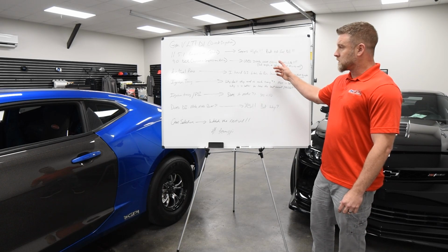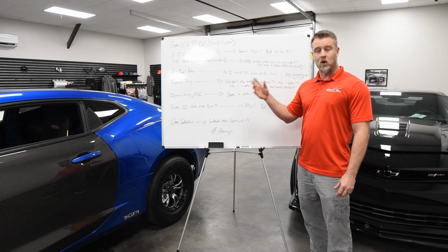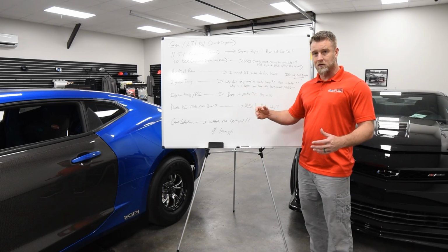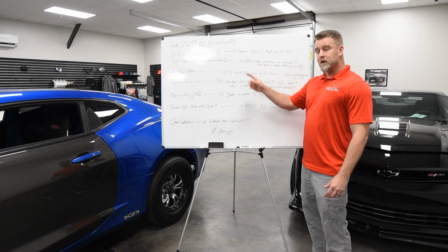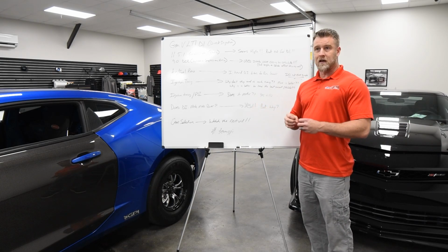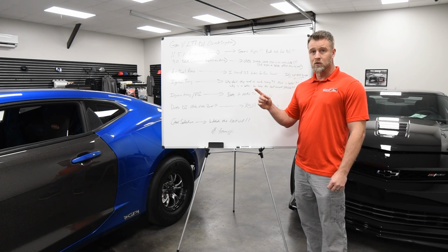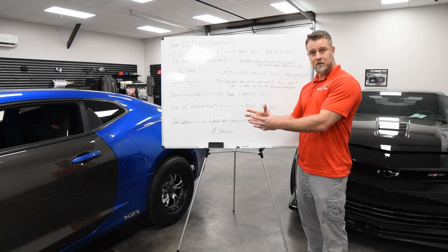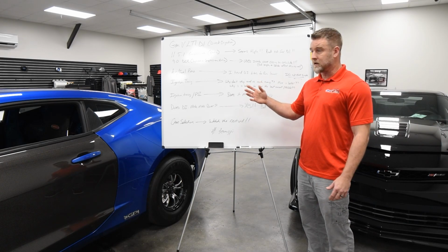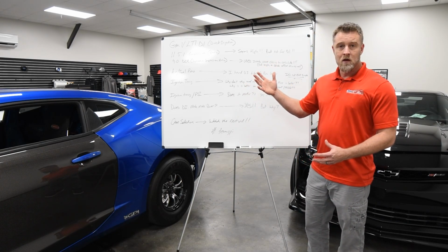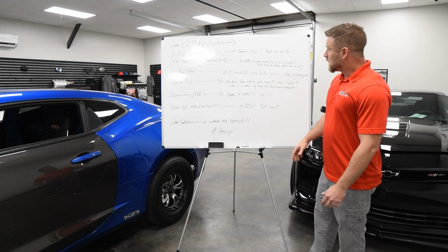And that's something you still have to worry about a little bit with direct injection, with not having any fuel cleaning the backside of the intake valve. You do get more carbon buildup, but that's just a byproduct of the direct injection engine. So really, putting the fuel in the chamber allows it to have great atomization and a cooler charge. You're able to inject less fuel because you're wasting less fuel to make it there. And they just burn a little bit cleaner in that aspect. I mean, it just will take a little bit more compression and cylinder pressure than a port-injected engine will.